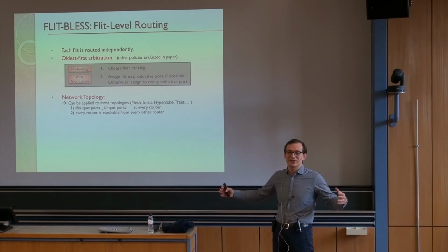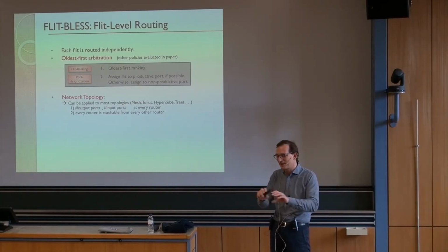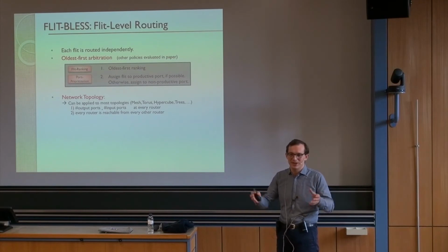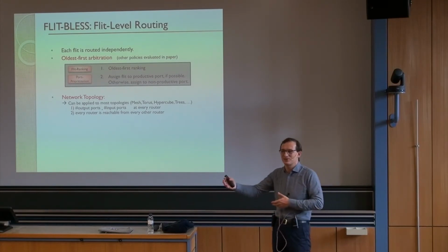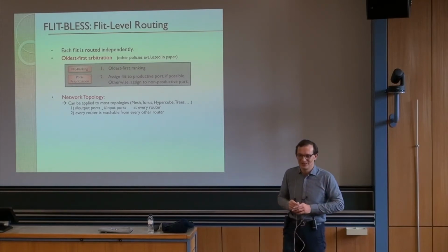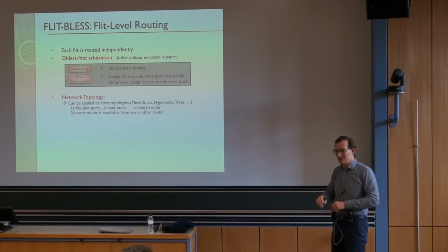You normally wait for the entire cache block before you do something with it. So you have buffering allocated for the entire cache block. Let's say it comes in 8 flits. You wait for all of the 8 flits before you do something with it. Does that make sense? Because you usually write to your cache at the granularity of a cache block. So we're going to exploit a lot of on-chip advantages. But that's a very good point.